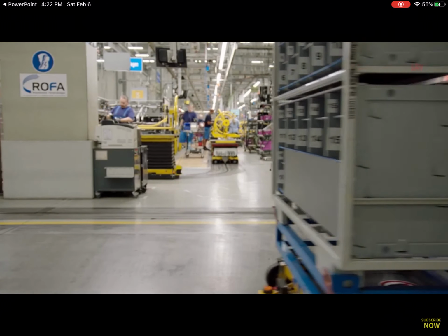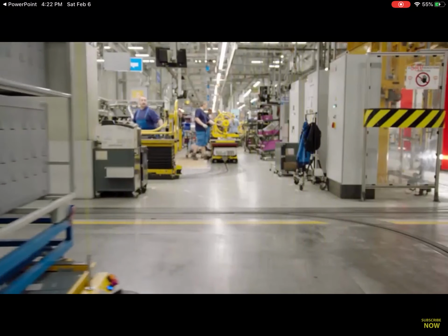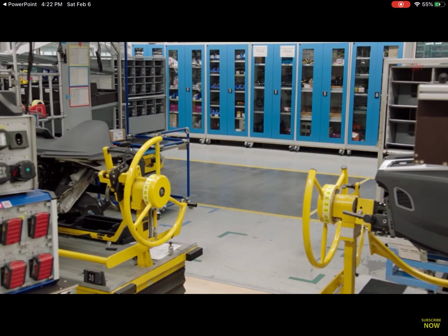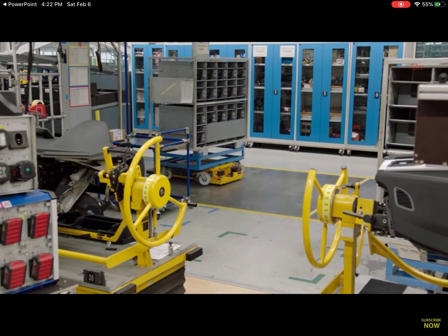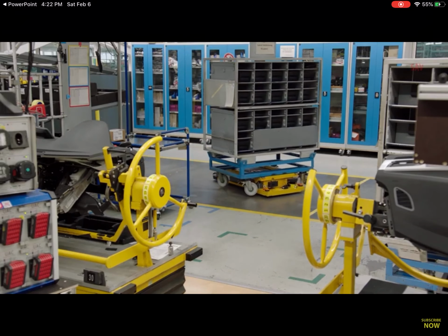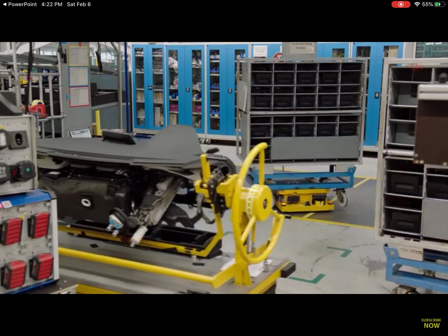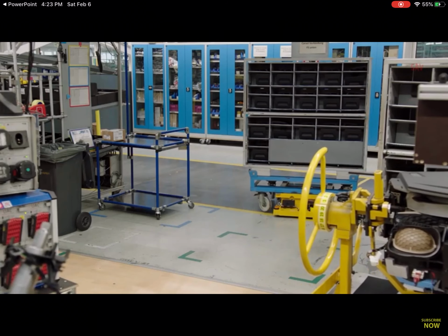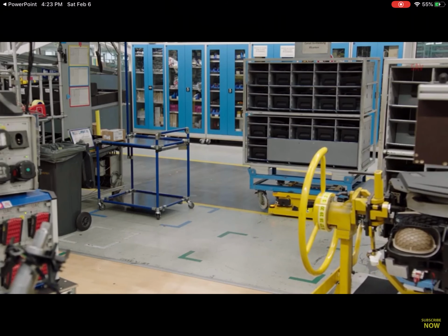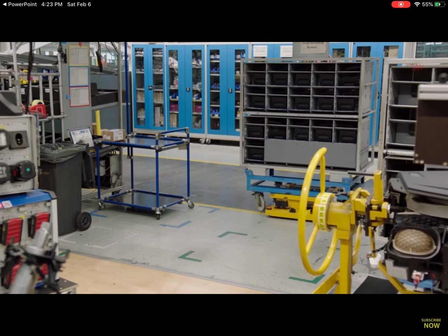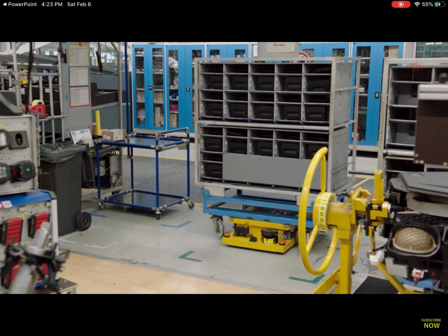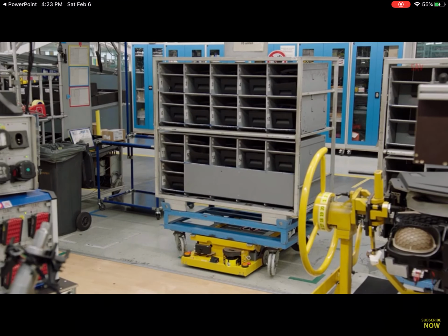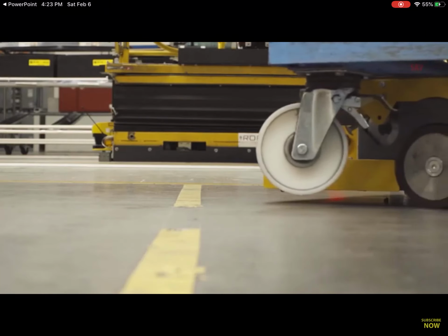So another safety protection is on top of the AGV. Sometimes you can add a light for some of the warnings. For example, if it has some kind of potential hazard or environment that might damage things, or it is getting too close to the human worker or some other obstacles, then the light probably can give some of the warnings. If you do not use light, you can also use sound or a combination of both sound and lights.